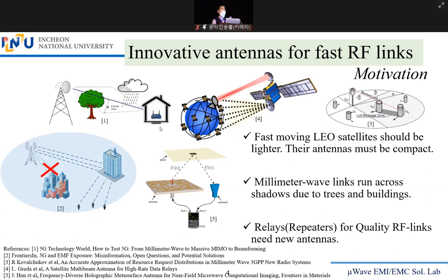If this frequency of interest is low, such as 2.4 gigahertz, such as Wi-Fi or wireless LAN, or the low frequency of 5G, it doesn't matter. But the thing is, you can see a tree that blocks the signal when we change the frequency from low to high. The signal strength at the receiver side will be much damaged and disturbed by precipitation from the clouds. This is quite common in the Ka band community.